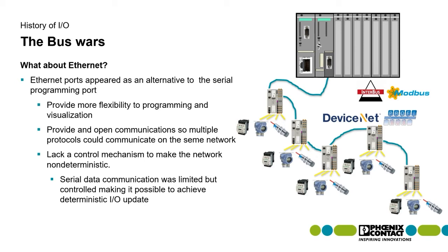And because their technology won the concept, we realized, well, all right, we're using our serial networks because they're very deterministic. Ethernet has a really cool open flexibility that we want to take advantage of, because me as a programmer, I'm lazy. I don't want to go out there with a serial cable hooked to my computer and plug it into the PLC to program it, because back then I wasn't walking around with a laptop. I was walking around with a big old desktop computer. So I had to drag everything out there, drop it down, and then plug the serial port of my computer into the serial port of this and download my programs. But if I used Ethernet, Ethernet allowed me to network my PLCs and get that network cable all the way back to my computer, and I didn't have to leave my desk.